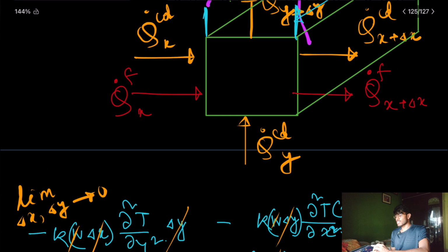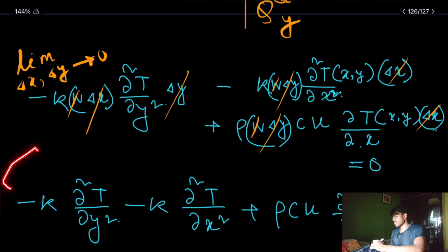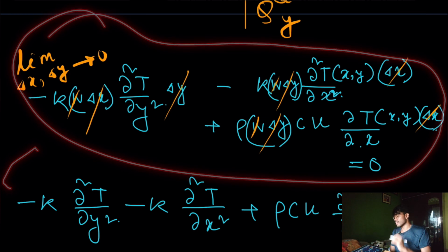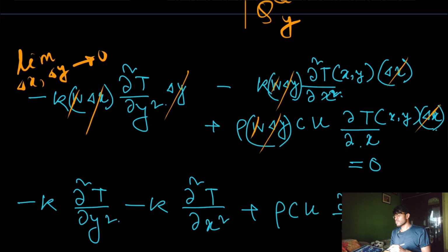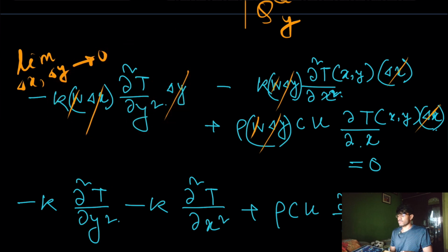Okay, now the next point. In the first part, it is given that you have to derive the two-dimensional temperature profile, and in the second part, it is given: now if the temperature distribution is neglected along the y, along the thickness, then what will be the case? Then some students will think that I have to do some manipulation in this governing equation. And what they will do is, because my temperature profile is not varying with y, I will just make this 0 and that will be my answer. No, that will not be your answer.